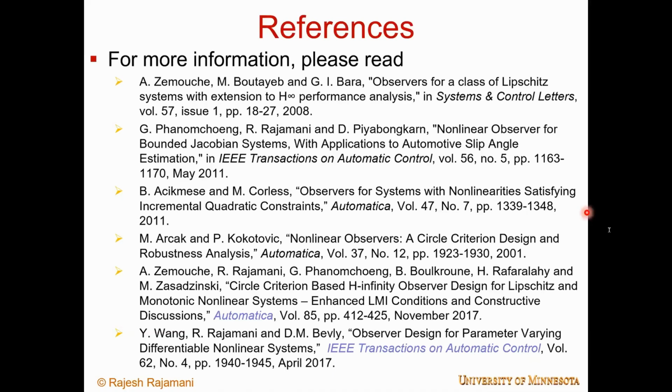Okay, continuous and discrete time systems. There are different papers on discrete time observer design that have been published as well. Oftentimes, the original equations of a system are continuous time equations, and sometimes they are discretized for various reasons. If you have a processor with high sampling frequency, then I think it's fine to design the observer in the continuous time domain and implement it in the discrete time domain.